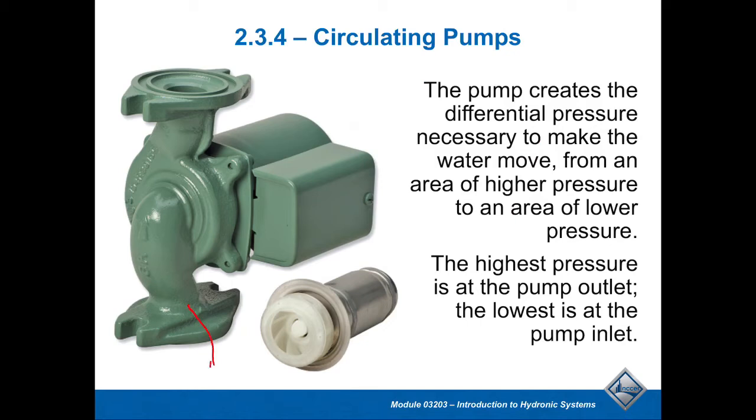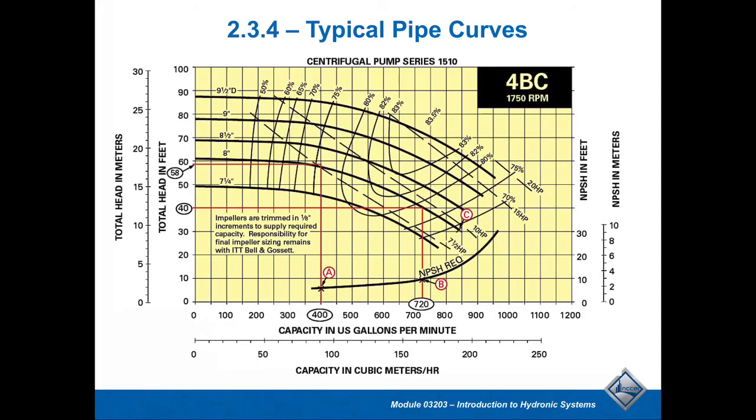In this picture, I want to point this out. There's an easy way to tell the inlet to a pump. On this picture, the inlet to the pump is this bottom little flange, and the water flows into the inlet volute and goes directly in here, where the water gets spun and flung out into the discharge. So when I am looking at a circulating pump, I'm feeling or looking for this little part of the system, and that tells me to follow it backwards and I'll see that the water flows in this way, and that's usually how you want to do that.